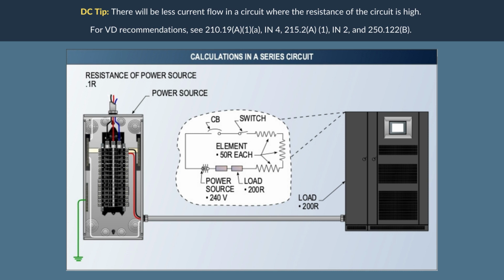Notice, the voltage drop across any resistance of the circuit may be easily found due to the current being the same through each load. For example, the voltage drop in the power source can be found by multiplying 0.6855 by 0.1 resistance of service as follows. In step 1, finding voltage drop, Vd, which is the voltage drop, equals 0.6855 amps, multiplied by 0.1 ohms, which equals 0.06855 volts. Therefore, the voltage drop in the power source is 0.06855 volts.